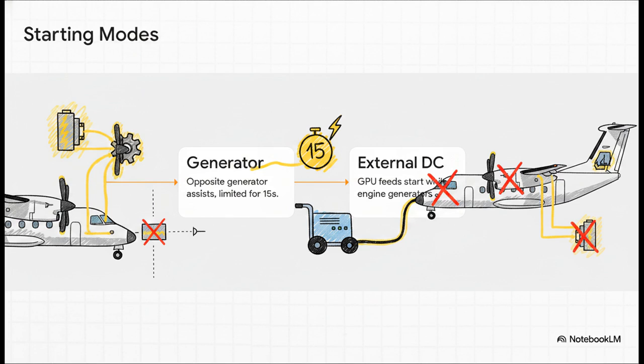Finally, if you have an APU installed in the tail cone, its starter/generator connects to the right main feeder bus to supply power in parallel with the nose batteries. Just remember tail to nose. The tail APU pushes power all the way forward to help the nose batteries.